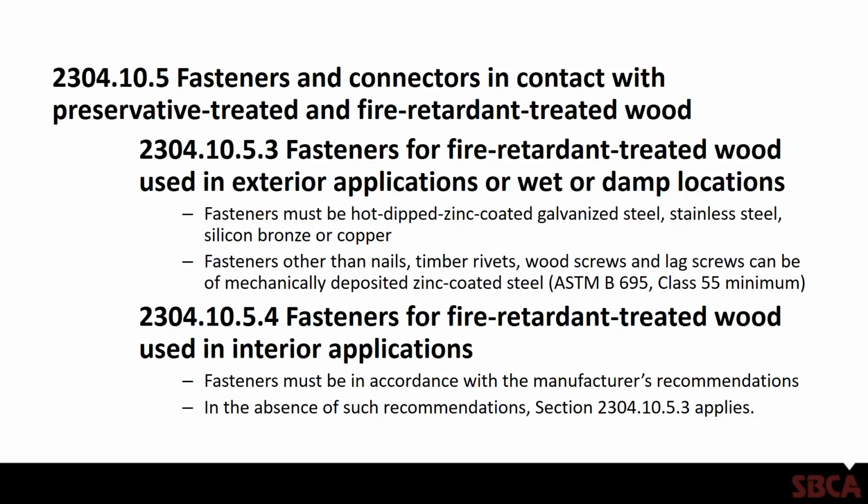And if you're using connector plates, then you're allowed to use mechanically deposited zinc coated steel. Now, typically for interior applications, you need to refer to the chemical manufacturer, the treating company's recommendations. And if they don't have any, well, then the code kicks you back to 10.5.3 and using some type of galvanized steel, or, like I said, stainless steel, silicon bronze, or copper.